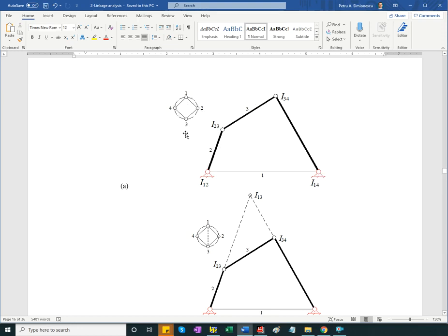Now this diagram also helps us direct our search. So here, missing are instance centers 1, 3, and 2, 4, and they can be found in any order, either 1, 3, or 2, 4. But in general, in order to progress with the analysis, and this is important, so you want to pay attention, you're looking at triangles that miss one side and they share that side.